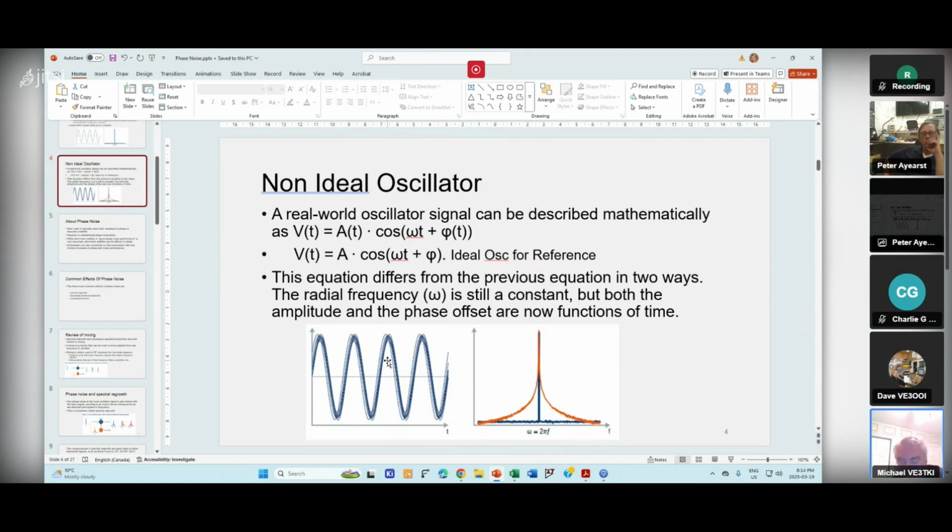Anyway, yeah, okay. If you have an analog oscilloscope, for example, and you see this jitteriness going on, you can actually trim the trigger point. Yeah, and that should clean it up. But I don't think you can do that with phase noise. It all depends how severe it is. It also depends on what's causing it too.